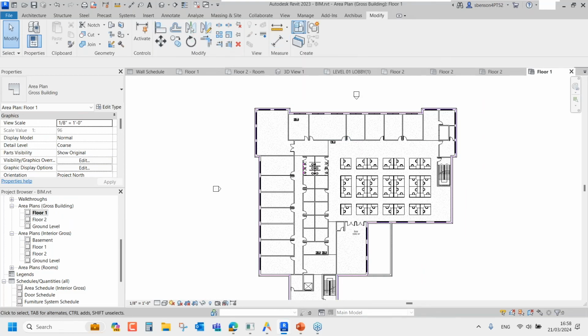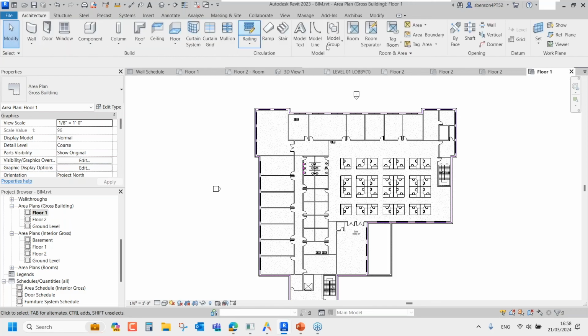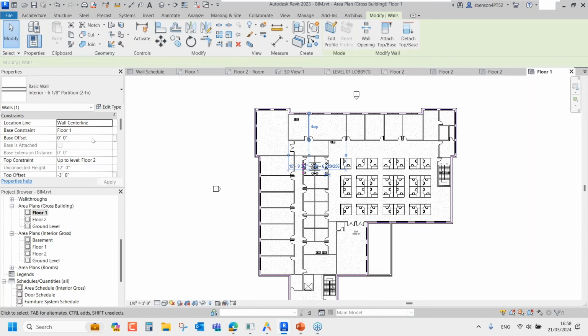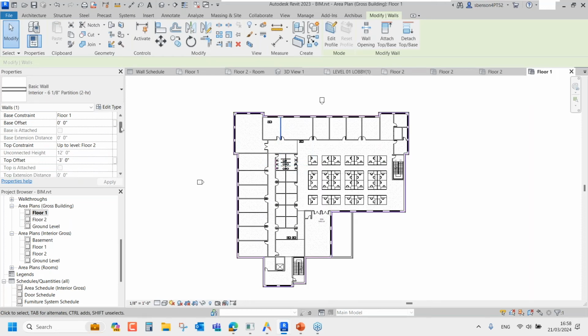That's where you have some drawing tools here that you can use, for example, for creating area boundaries and room boundaries and so on. There are things like room separation lines that you can use to polyline, or area boundaries that you can draw. And there's even functionality in the individual walls that determines whether that wall is going to be included in a room or not.